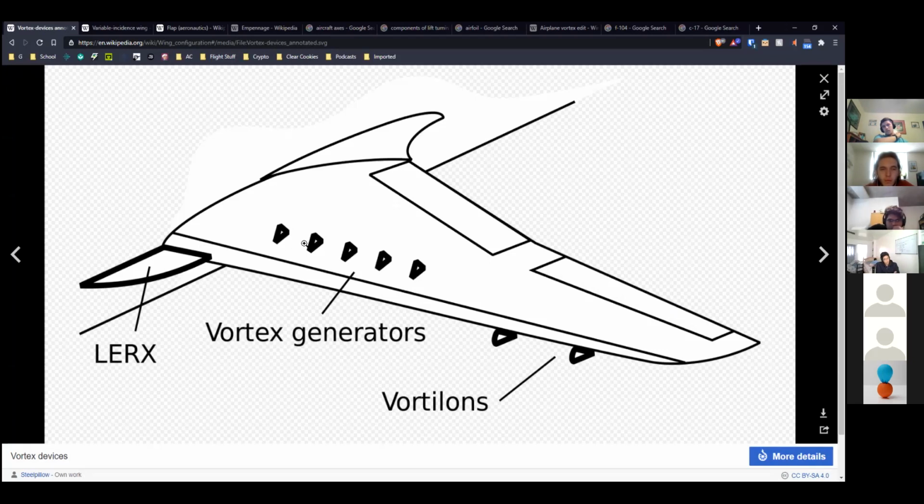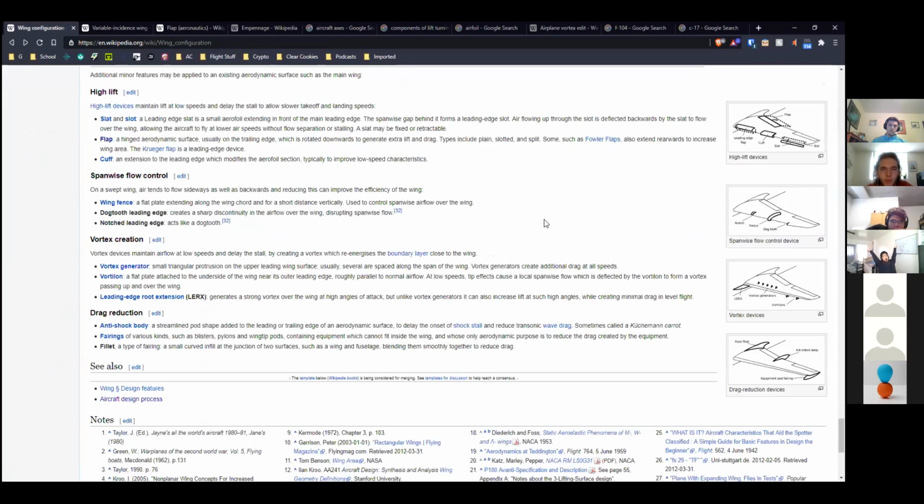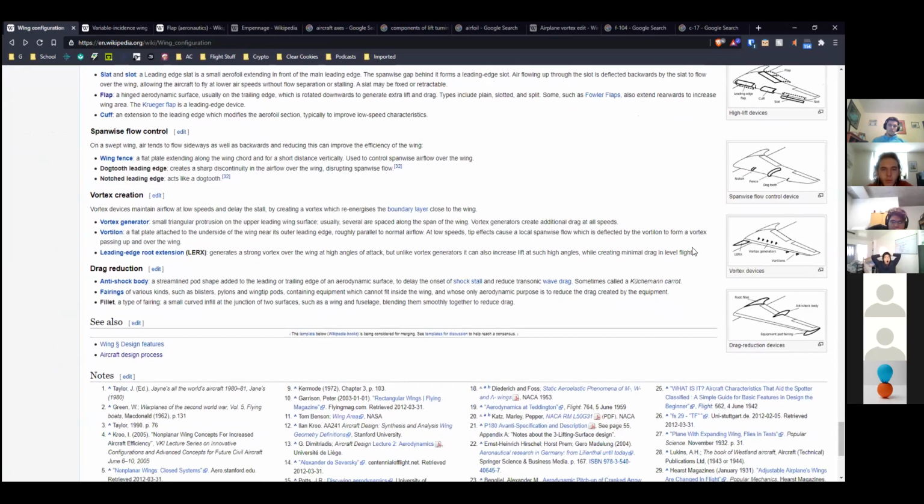The reason vortex generators are used on cars and on low speed aircraft is that they can keep flow attached longer and therefore have an overall smoother flow around the whole vehicle if it's made turbulent intentionally by VGs, as opposed to letting it go from laminar to turbulent on its own and then have chaotic breakdown and detach. We don't really use them, but you're welcome to look into it because we do actually fly in the regime that I think they could help.